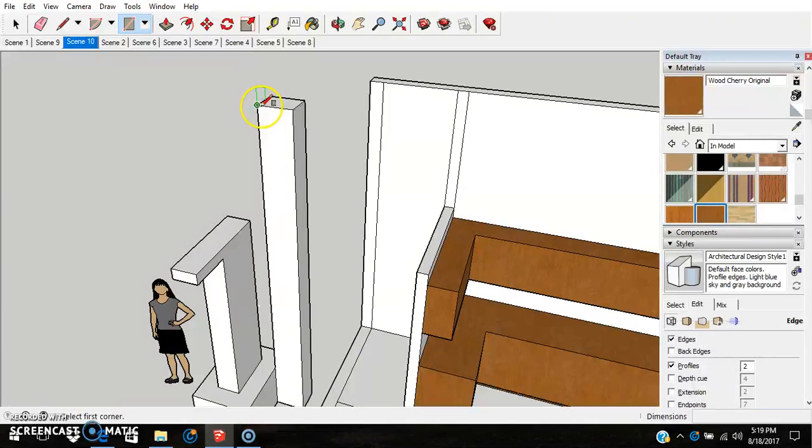So now the interior ceiling would be 5 inches down. So again, we're going to put comma 5 and put that on there, and also use the push-pull tool, raise this out so we can have something to measure off of. That's a little bit easier than just the lines.